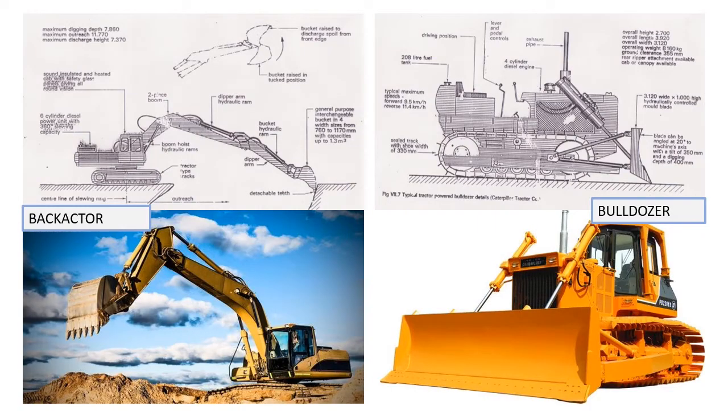The first plant that we have here is Backhoe. These machines are suitable for trench, foundation and basement excavation and are available as a universal power unit based machine or as a purpose designed hydraulic unit. They can be used with or without the attendant haulage vehicle since the spoil can be placed alongside the excavation for use in backfilling. This machine will require a loader transport vehicle for travel between sites.